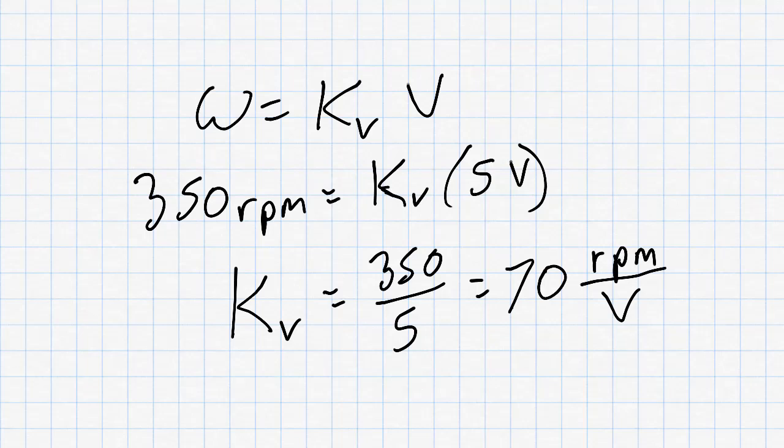Let's try and do a test to get the motor velocity constant at other voltages. Now here we'll run into a problem. The PSOC is a digital controller. All microcontrollers today are digital. That means that inside, this thing is basically made up of switches. Each of the pins on the PSOC can either be on or off, but they can't be anything in between.